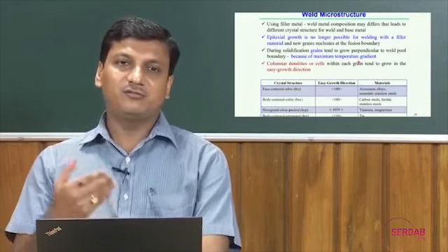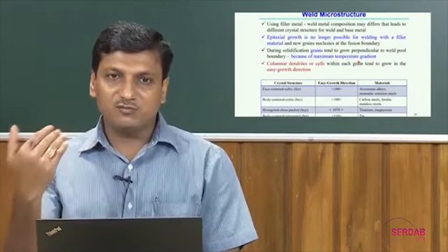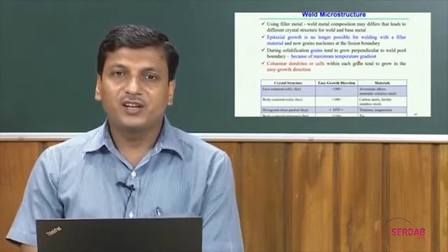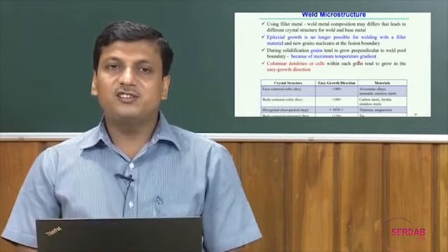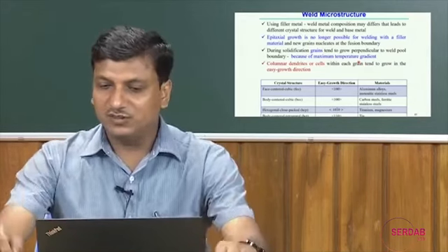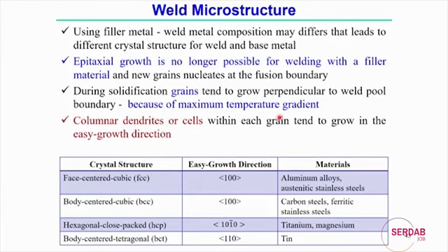So adding the filler metal doesn't promote epitaxial growth, and new grains nucleate, basically forming at the fusion boundary when there is an addition of other alloying elements, or maybe you can say with the addition of the filler material during the welding process.